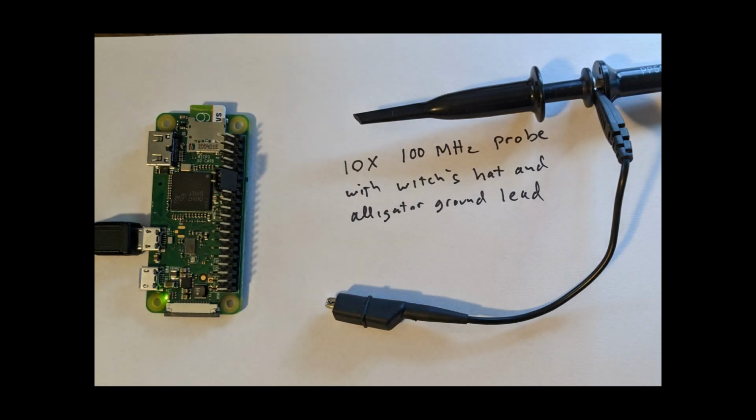The Siglent's higher bandwidth gives us more possibility of seeing signal distortion that's caused by the probes themselves. For example, the ground lead on the probe shown here, those are somewhat famous for acting as inductors, and then when you connect it to the system under test with a fast rise time, the fast rise time has high frequency energy that can incite a resonance. And then you can see this as ringing in the signal that you're trying to probe. That ringing isn't necessarily really there. In fact, it probably isn't. It's caused by the probe.